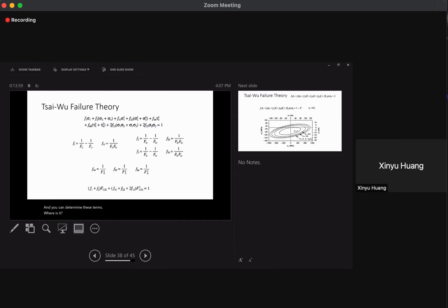Oh, right here. Similarly, you can apply the test in two directions. In the matrix direction, you have tension and compression. You can determine these terms, and this is an out-of-plane direction. And these are shear conditions. This includes out-of-plane shears. For in-plane, it's simpler. For out-of-plane, it includes these things: the in-plane shear and two out-of-plane shears. You have two out-of-plane shear strengths and one in-plane shear strength.